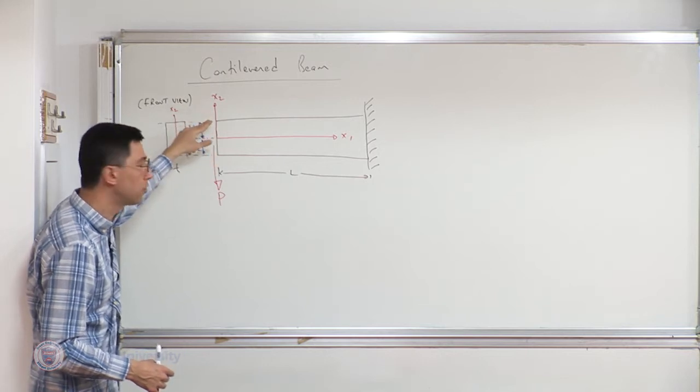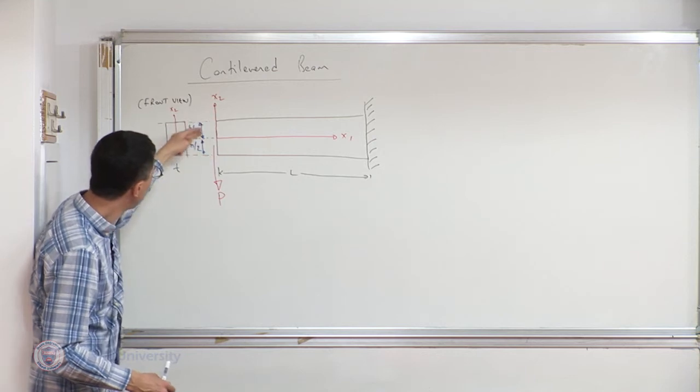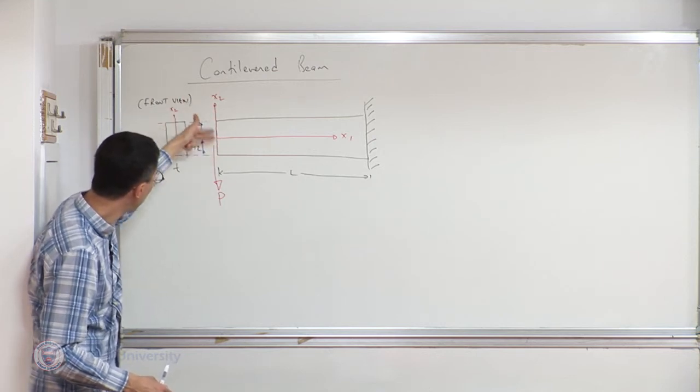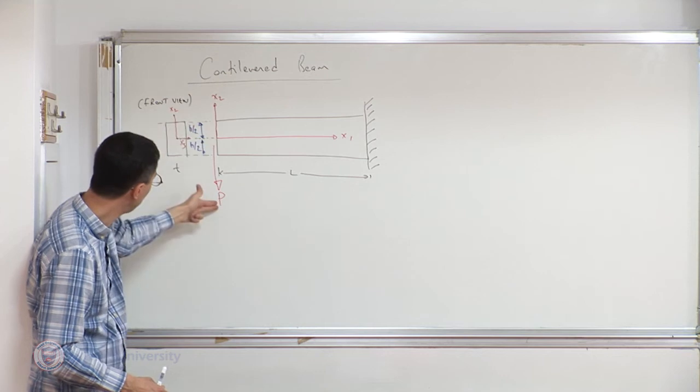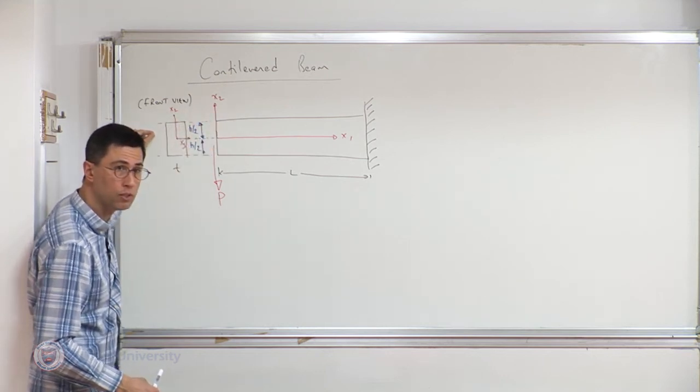So it's not necessarily traction-free. It cannot be because there is a net force. But the statically equivalent representation of that stress distribution is that there is a vertical force in that direction. Net moment is equal to 0. Net normal force is equal to 0.